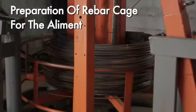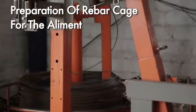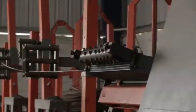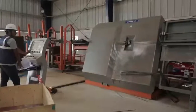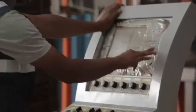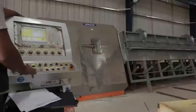Preparation of rebar cage for the element. It is important to ensure that reinforcement steel is tested and inspected before use. The number of bars of required shapes and length are mentioned for each element in the respective drawings and bar bending schedule. Bars are bent and cut in a bar bending machine, where the bending and cutting details are entered as per the drawing requirements.